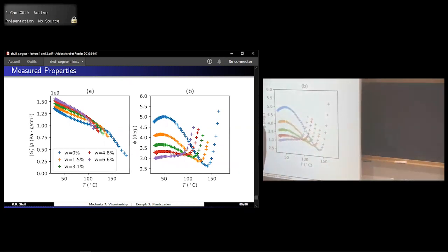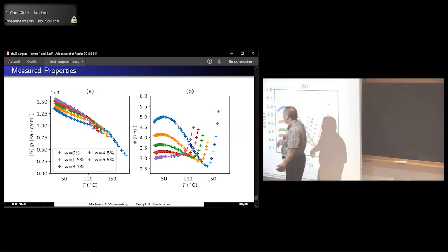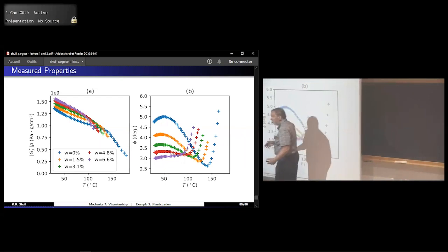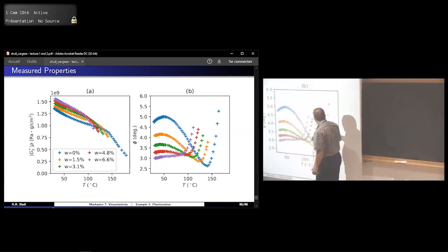And the way of thinking about this, which I think is mostly accurate, is that the modulus goes up in the glassy phase because you're basically filling up small voids. You can think about it in this way. But it's a pretty clear increase in the modulus. But the glass transition itself is still going down. So you can actually see that better from here.